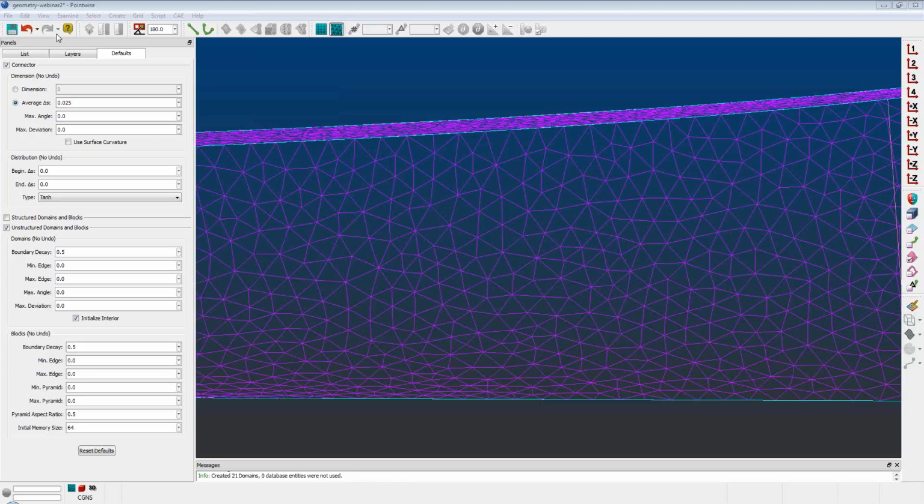Okay, thank you. And just a quick add-on too, Isaac. You can mix and match analytic and STL files in Pointwise. You can keep appending, and you can append whatever format you want, and have a hybrid type of geometry. Right. Thanks.